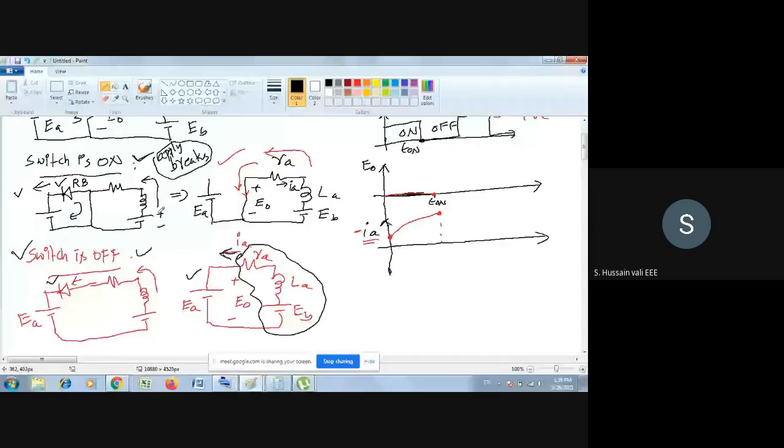Like in previous classes, I told you that rectifiers, AC voltage controllers, inverters and resistors are also there. Using any of these you can control your motor, and one of the options is the chopper. Now there are several types of chopper. I am explaining the first quadrant and the second quadrant, but actually you don't use the first quadrant chopper exclusively. Wherever you want chopper operation for a motor, you use the four quadrant chopper, not the first or second quadrant chopper. I'm just explaining each quadrant chopper individually. When I explain the fourth quadrant chopper, you will understand why it is so.